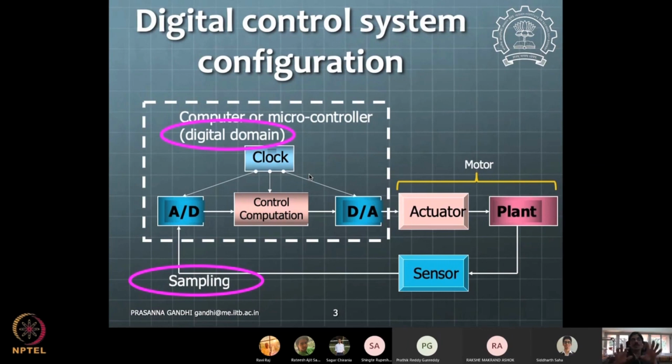But as a mechatronics engineer, we need to be aware that at some point I may not have that flexibility of having fast implementation, so that the system could be considered continuous. Under that situation, we need this analysis of digitization. So we'll have these two parts coming up. One is your sensor. Typically, in our case it is a digital sensor, but analog sensors will have the issue that you sample this sensor signal. So the sensor is read every sampling time, and the actuator is given input every sampling time.